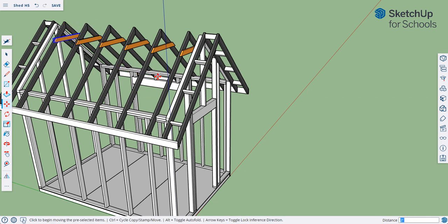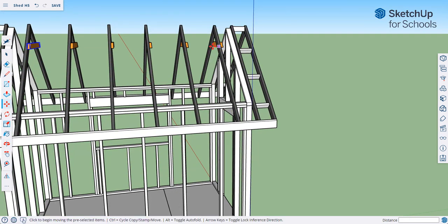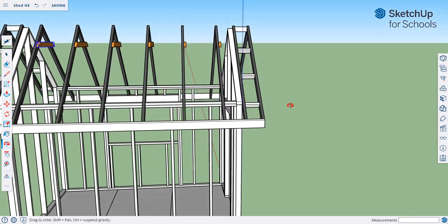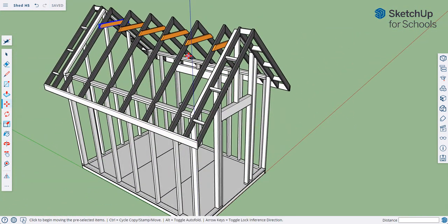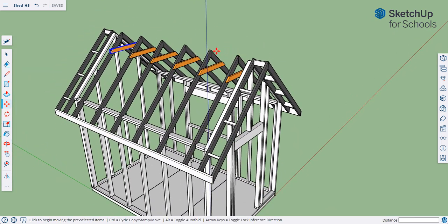Now, you don't have to do it on the outside. That is just for design purposes. But the orange ones are structural. So I'm going to click Save. Do the collar ties, and that will enhance or create more structural support for the roof. So again, how low this is depends on what the engineer would say. For the meantime, we're just going to put it 12 inches below the very top. Okay, so do that.